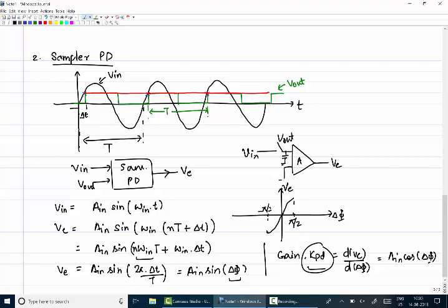for all the small signal analysis, you need this. It is like an operating point analysis. You do an operating point analysis for a transistor, right? When you use it in a common source amplifier or something, it's the same thing. Once everything locks, you need to find the small signal gain of each of the blocks to analyze later for the noise or any small disturbances in the system. Okay. Now, what happens in this?